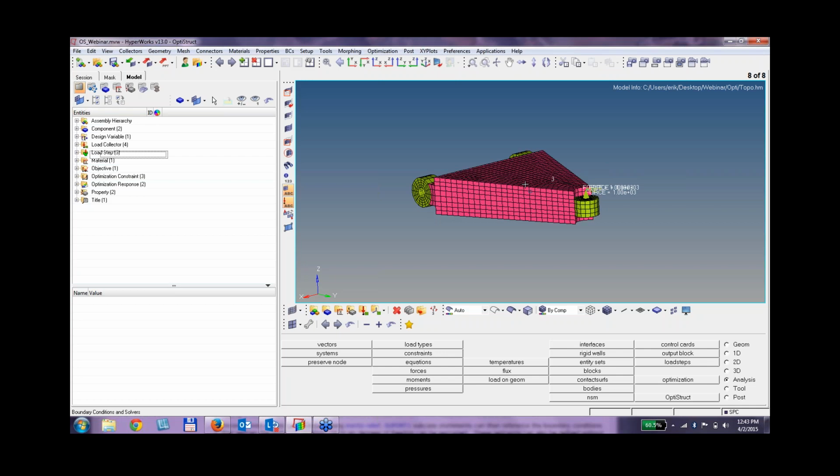Now, I want to find out what material of that is necessary. Now, we as engineers tend to over-design the heck out of things, for a good reason. We don't want our car parts breaking, or even worse, we don't want our airplane parts breaking while the plane is in flight. So we over-design things. Well, the optimization code doesn't have that limitation. It knows how the force is progressing through the model. It knows where to put material, and that is what topology optimization does.